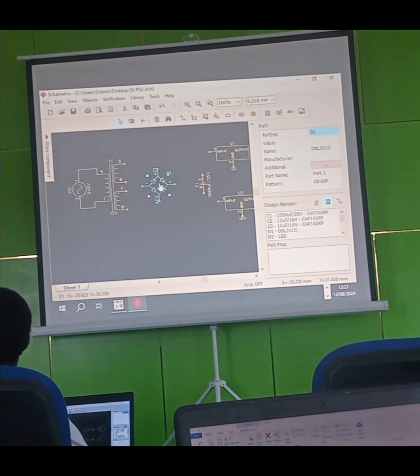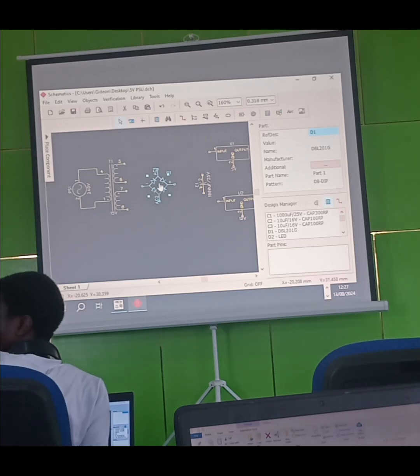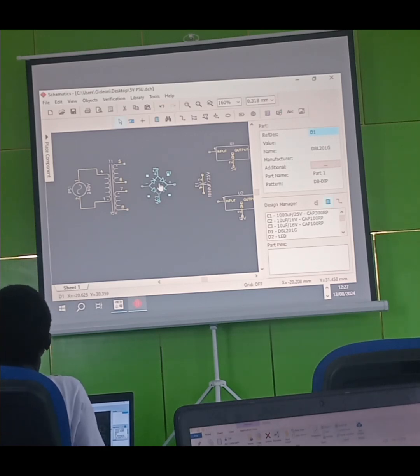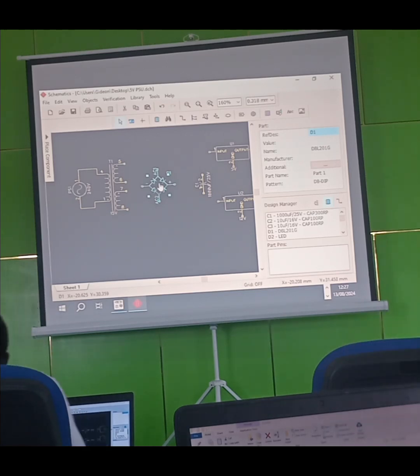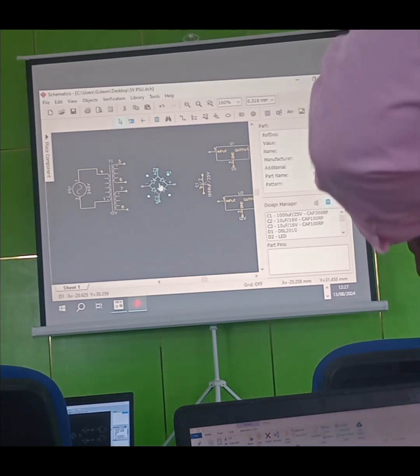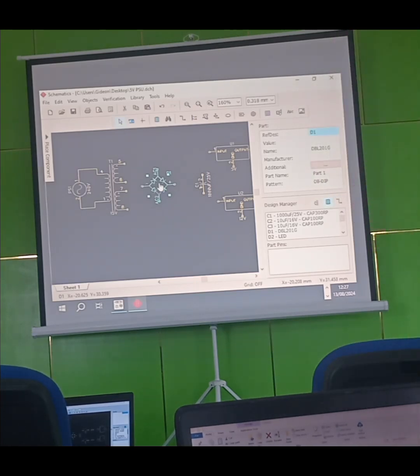It stresses the voltage regulator because it is stepping down that higher voltage, and that voltage difference affects it. Let me explain to you, it's a calculation. The 7805 can take as much as 32 volts.